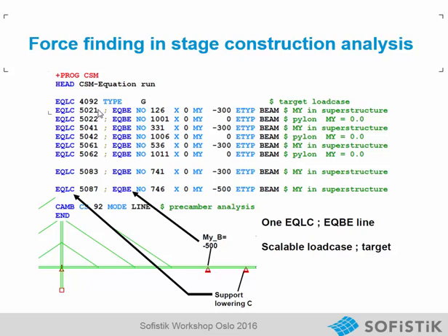If we stress the first cable, that is this cable, we can best optimize the bending moment here, because if we stress it, we directly affect this bending moment. And also here, for the last support, lowering can affect best the bending moment at this position.